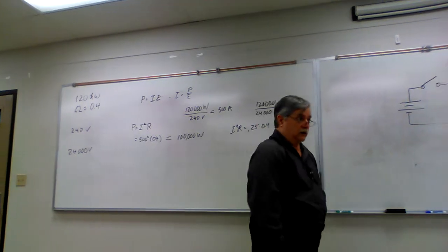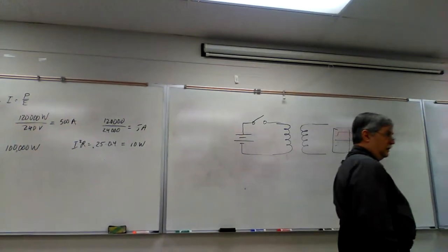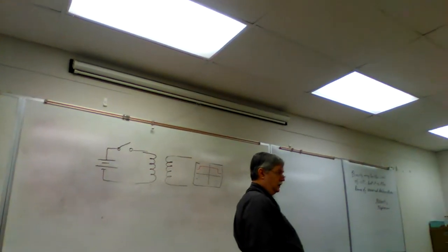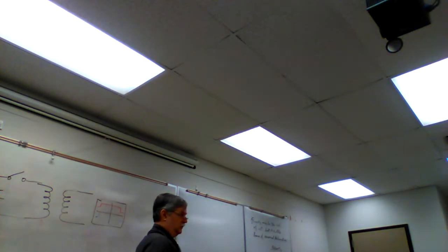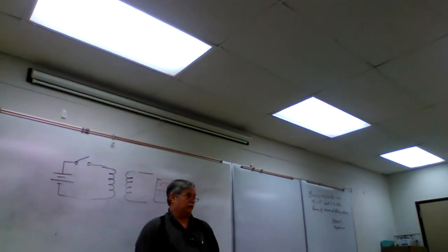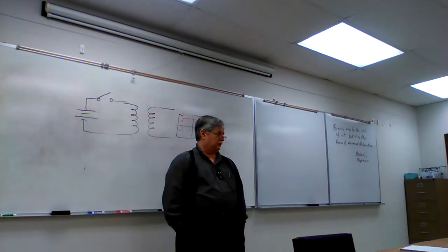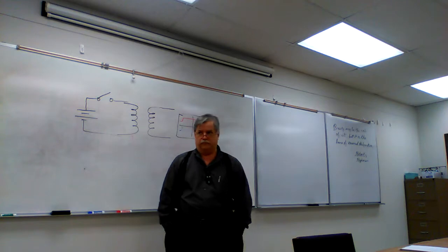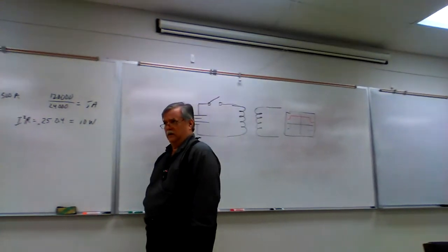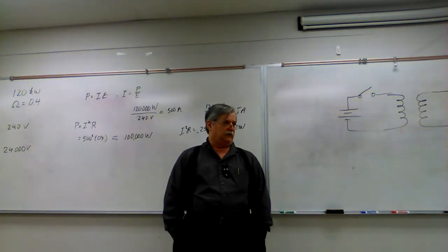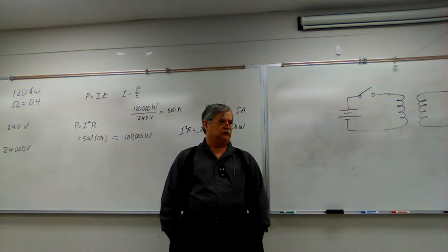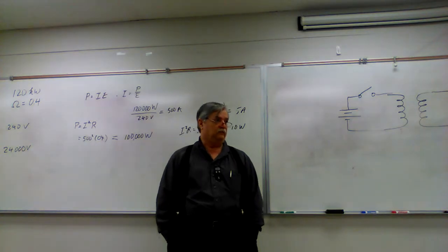Everybody, yeah, go ahead. I was going to ask about the turns, because I know when we were talking about the ratio, like if you needed a 1 to 2 to step it up, what's the difference between doing 10 turns and 20 turns or 100 turns? It's going to affect the total resistance of the wires that make up the coils. In general, you want lower resistance and higher inductance, because that determines what's called the Q, or quality, of the circuit.